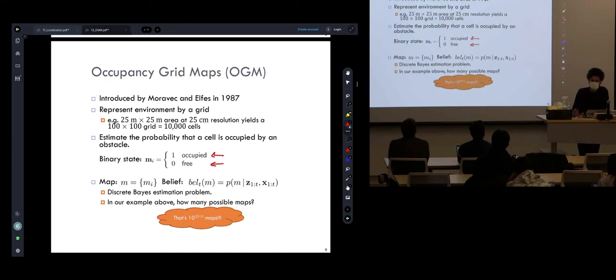So we don't form a state to build a traditional state estimator like a Kalman filter or particle filter, although you can do such a thing for each grid cell individually if you want, but never jointly. It is ultimately like a landmark is a position. That's right. So there are ideas to run tiny EKFs or particle filters to estimate some quantities for each cell. People do that, and you can consider a neighborhood if you want, but it's rare. It's never for the entire map, because that's just not tractable.